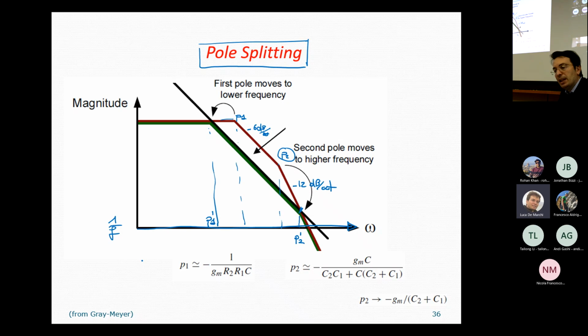So this means that after some simple algebraic calculations, the modulus of P2 must be equal to 1.22, that is 1 over 0.818, times omega null. Okay? So this is the positioning of the pole that we need if we want a phase margin equal to 45 degrees.